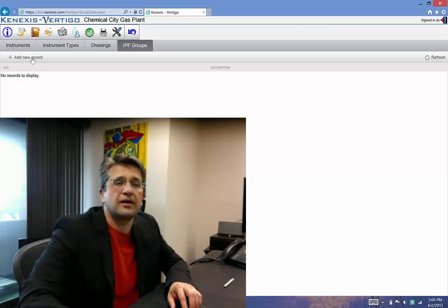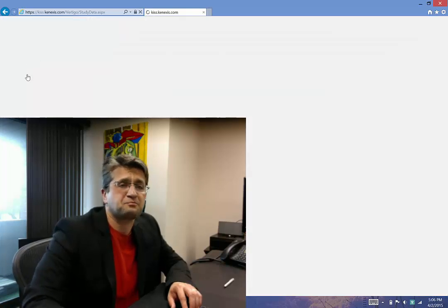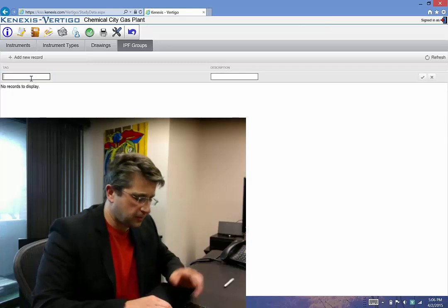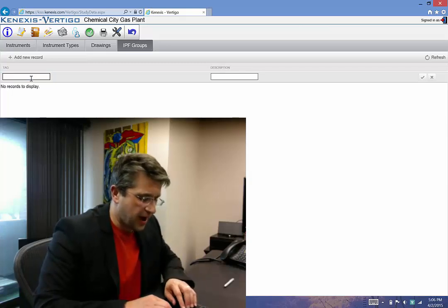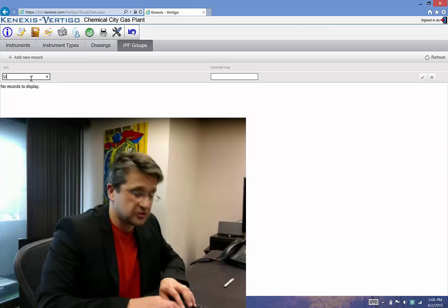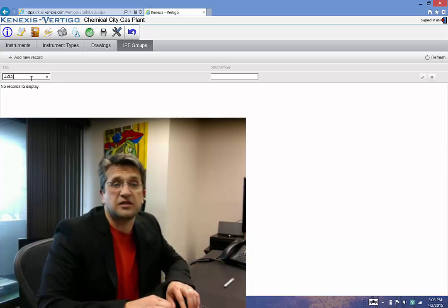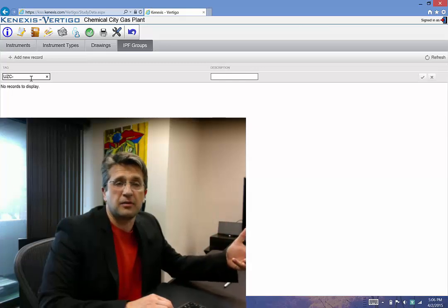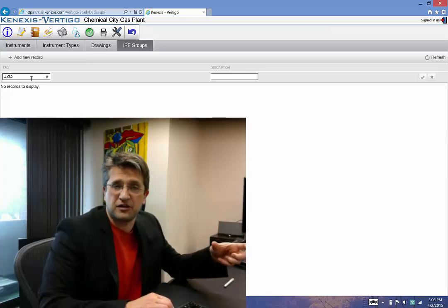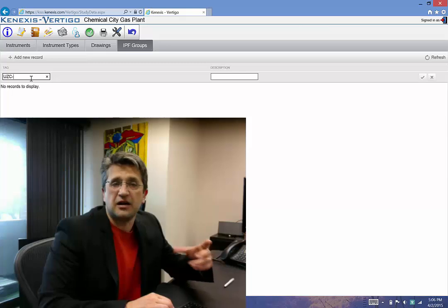So I'm going to go ahead and add a new record here and create an IPF group. I'm going to use standard ISA naming conventions. So a safety function is a UZC, which means it is U multivariable, Z for safety instrumented system, C for controller.